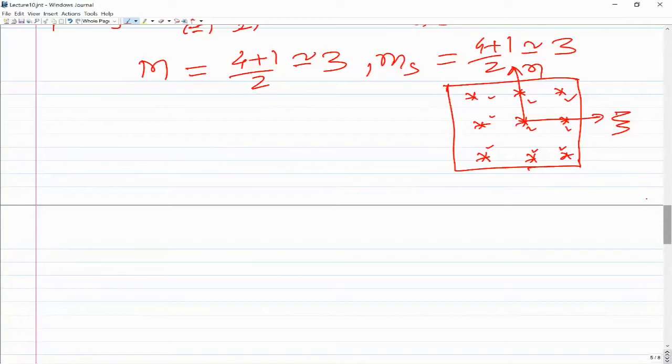Although we expect the deflection to reach the value we get from classical plate theory, if you use fully integrated shear deformable plate elements, meaning the full number of Gauss points m and ms as I discussed for evaluating the stiffness matrix, for thin plate problems, it under predicts the deflection, and that under prediction is known as shear locking.